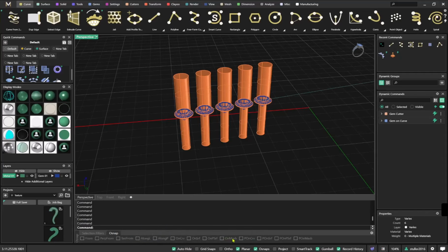As you can see here, we have on surface, on polysurface, and on mesh, right? And if you want to activate the between, you have to press Shift, not Control. So if you press Shift, you go to between. If you press Control, you can go to perpendicular, from, and this kind of thing.